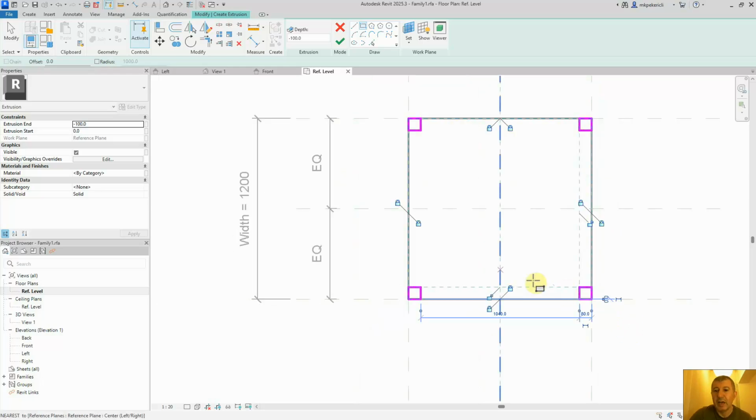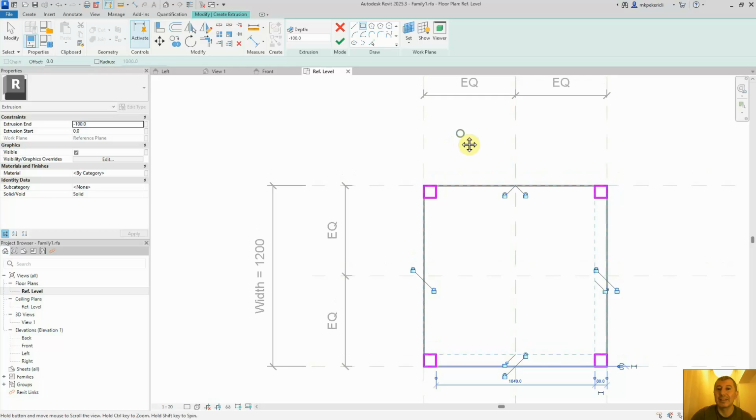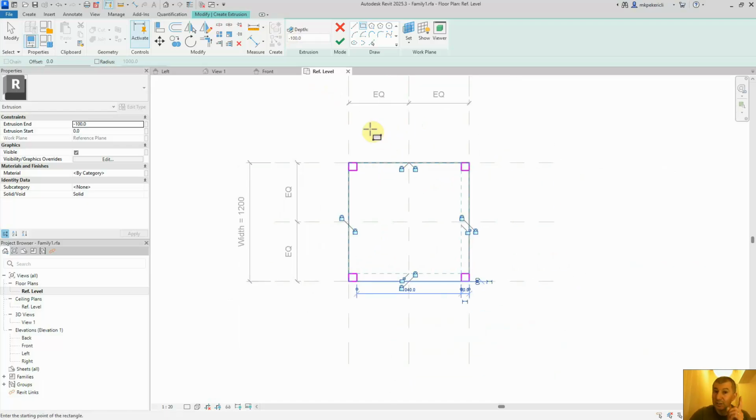Okay, now the next thing that I need to do is I need to set the thickness dimensions for these table, let's say legs. Okay, so for that, this is the tricky part, I have to be within the edit mode. Okay, create extrusion edit mode. I shouldn't be leaving the mode, and I use the dimension tool again. I click on dimension.